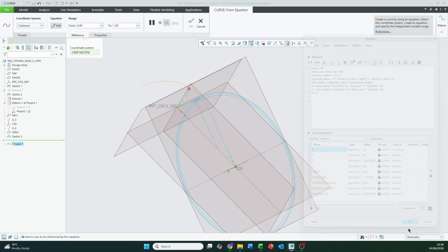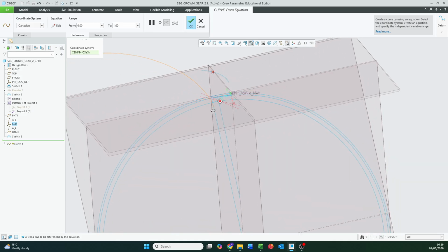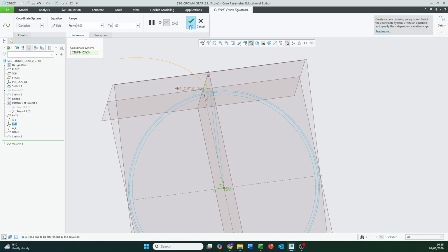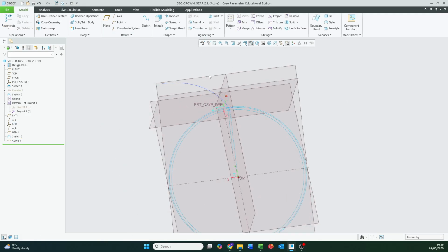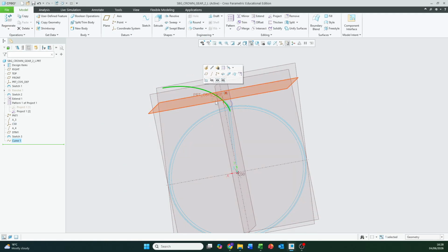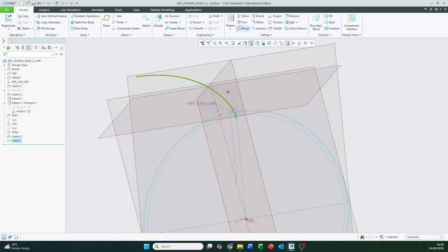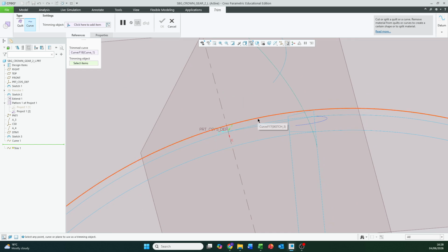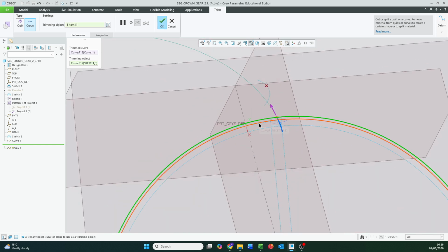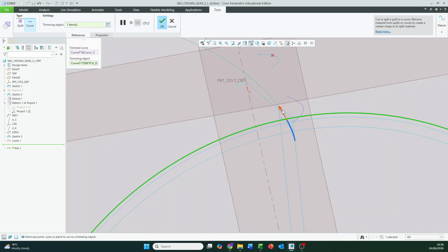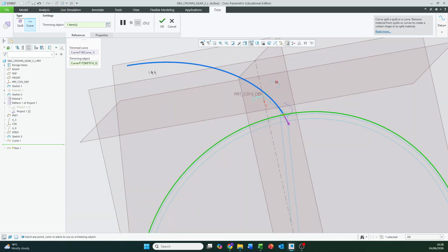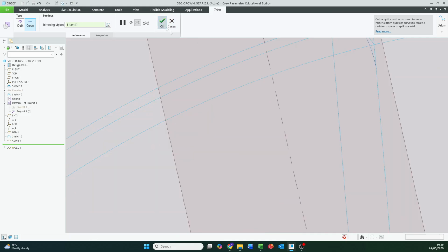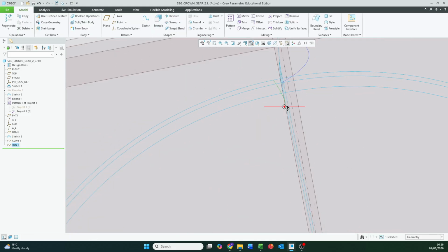Okay, and perfect. Okay, again, this is too large to handle right now, so we are going to trim this with the tip circle being the cutting, the trimming object. Flip the arrow. We want to remove this. It's the highlighted in blue section that was removed. Press OK.